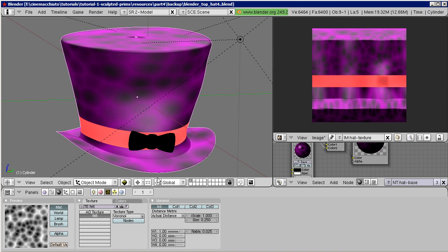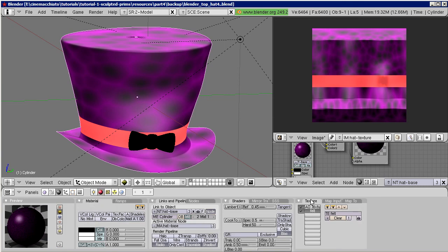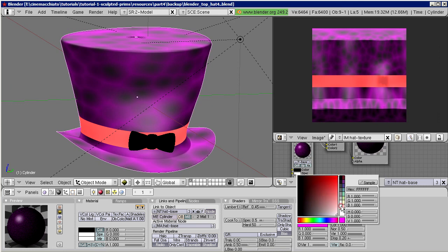Now let's go. Locate the noise size setting in the texture button section. Change the value to 0.02 or any other value to your taste. Switch to the material button section. In the Matte 2 tag, change the secondary color from pink to white. Then bake again.